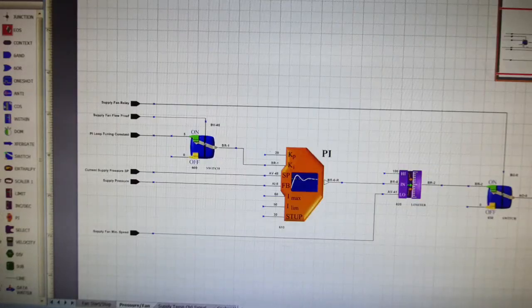That means कि ये आपका 1.4 inches of water column, 1.4 inches WC के static pressure पे आपको fan की speed को maintain करना है. Because as you know, AHU is an air handling unit which supplies air like 30,000 CFM based on the requirements of the space and the area it is serving, and then that goes into the ductwork. और ductwork के end पे आपको मिल सकते हैं variable air volume units, fan coil units जो भी हैं, वो secondary units जो particular spaces, particular offices या areas या rooms पे supply करते हैं air को.